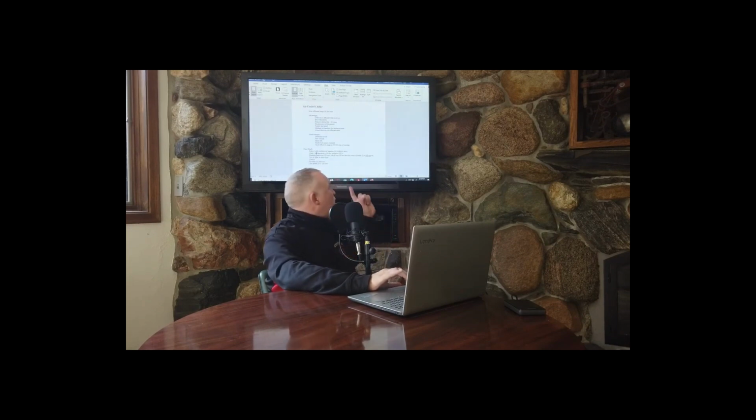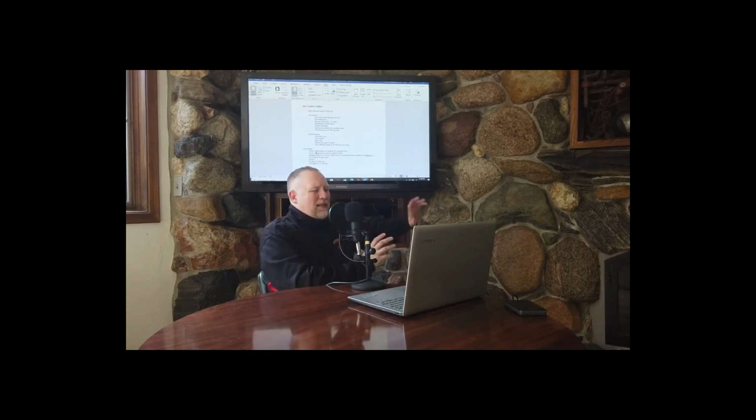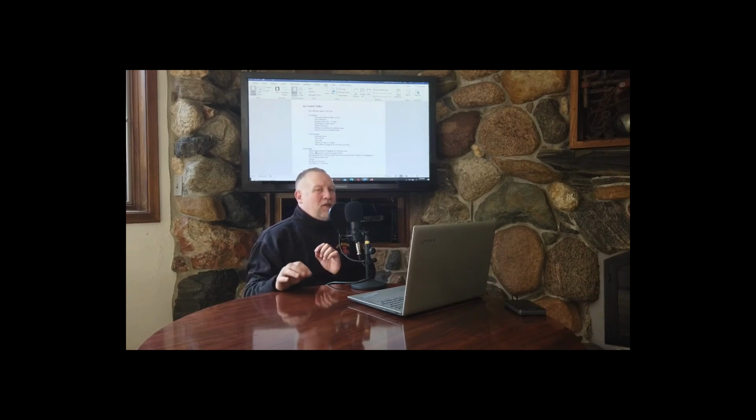Let's talk first. I'm on page 28. An air-cooled chiller. So I take a chiller and I sit it outside, like the one at DMAC, at the Hunziker Career Academy. I'm going to sit that thing outside. I'm going to make chilled water, and I'm going to pump that chilled water into the building. Now, there's some good advantages to this. I put the refrigeration cycle, the compressor and the thing that makes a lot of noise, I put it outside.